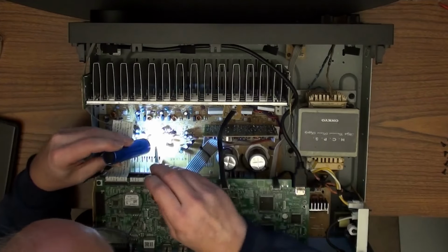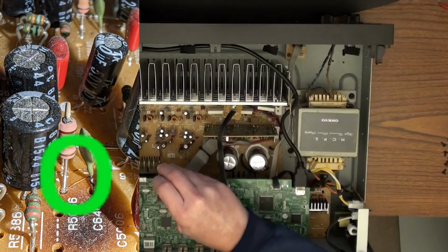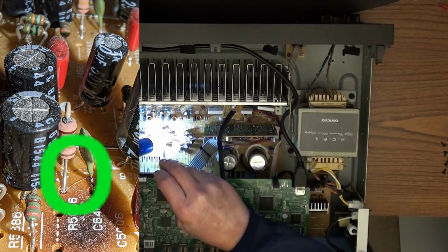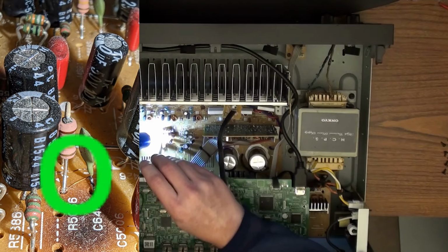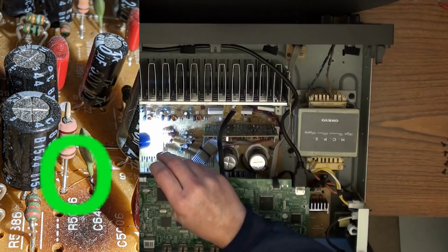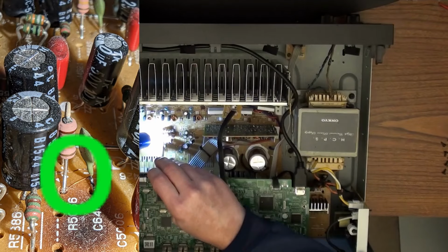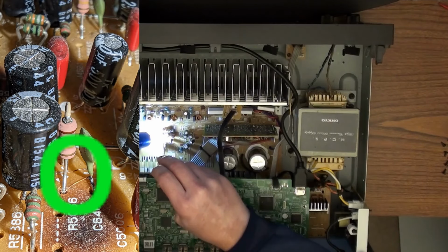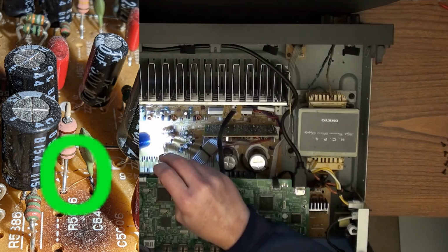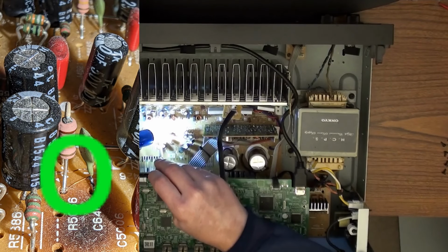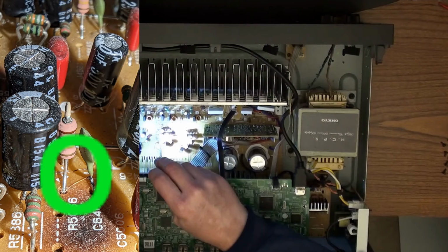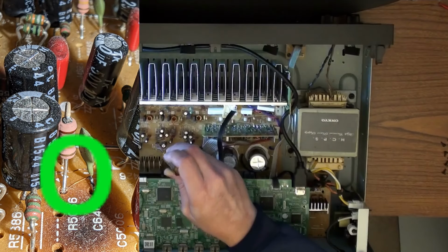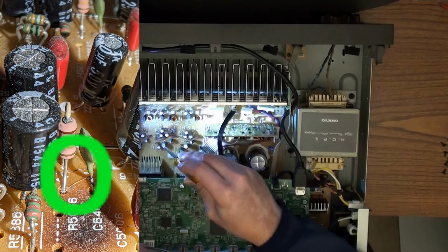Let's see, there's another one right here. So this is 3. And on that one, you can see that it actually is shorting together between the resistor and the green capacitor here. So that one definitely could be causing some kind of a problem. I haven't looked underneath to see if those are connected underneath. If these 2 legs are connected underneath, then it's not going to cause a problem. But if that wire jumps around a little bit during movement, or maybe it did move, I don't know, that could have caused a short. So that's 3.